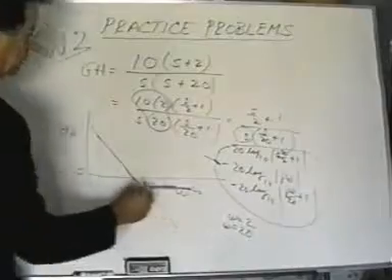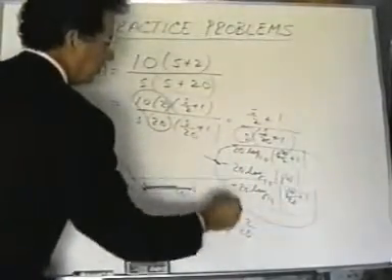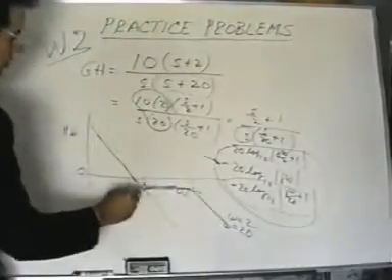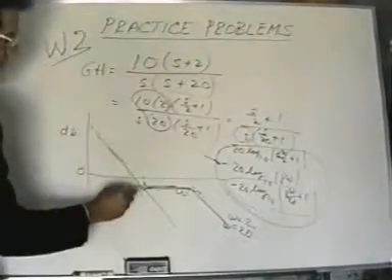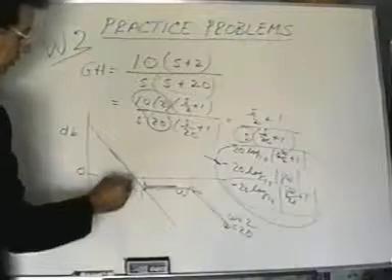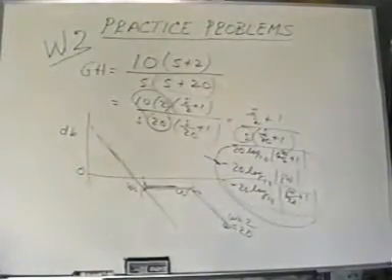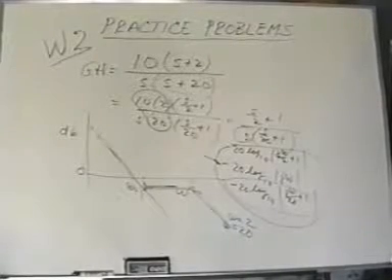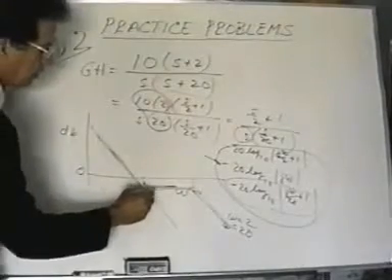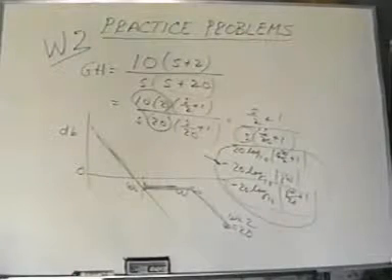And at 20, because of the presence of this last term, it will go down again at a slope of minus 20 dB per decade. So the curve of the Bode plot looks like this. The only point that's critical is that this is passing through 0 dB when omega is equal to 1. So it's a very easy curve to plot, and you would just draw one line segment, 2 line segments, 3 line segments, and we're finished.